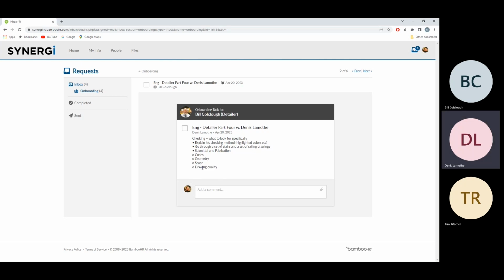So it limits us a little bit in terms of how we present our plans or elevations and whatnot, since by default it shows all lines for all items. But we'll dive into that a little bit, and we'll talk about things like overlapping dimensions, how to place your text, layout on your page, your drawings and your details to try and make it clear for everyone who's reading it what it is that they're looking for.